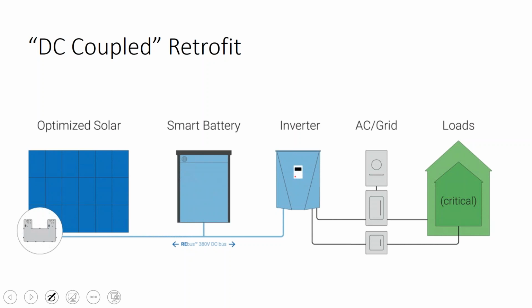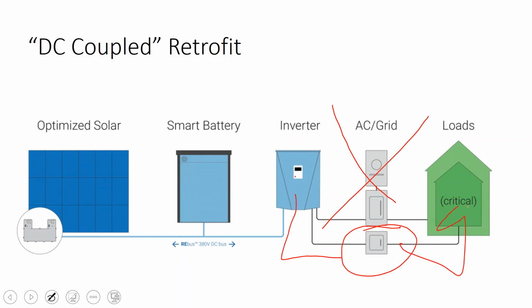So we're going over high-level stuff right now. We're going to get into the design brass tacks as we go along. What that means is that there are some innovative inverter companies out there that may not be designing systems to run a home off-grid, but instead may be grid-connected systems with a dedicated sub-panel. And so when the power goes out, they still power the sub-panel to your critical loads, but they don't power the entire home.